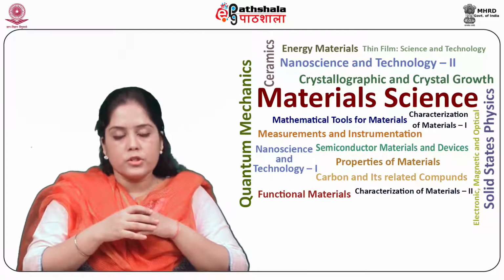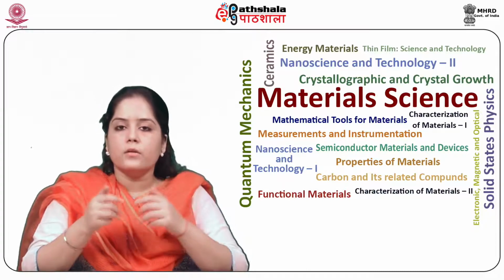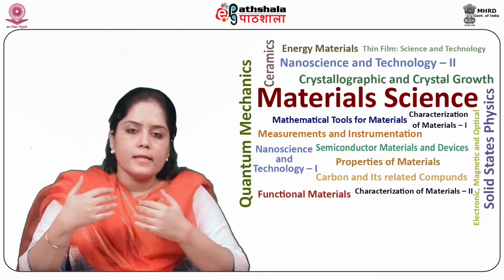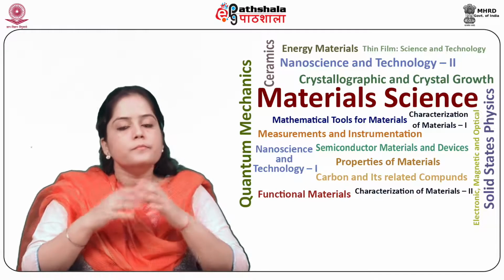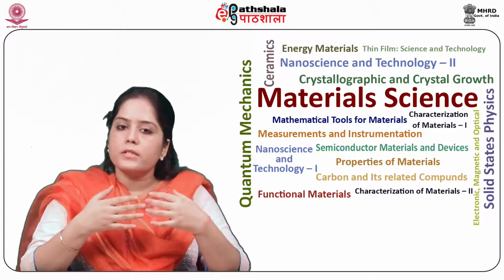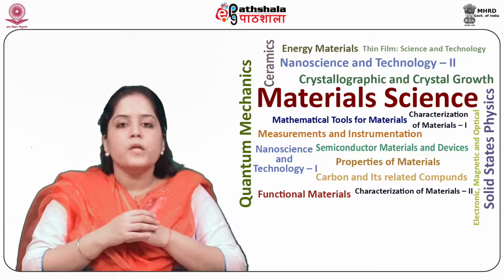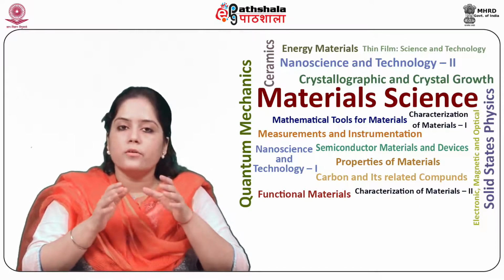microelectronic mechanical structure technique. As the name suggests, ENOS is some kind of electronic nose sensing the concentrations of various gases, similar to the functioning of our nose, which keeps on sensing the different gases and identifying the type of gas. Metal oxide based gas sensors are the most popular sensors in terms of ease of miniaturization and mass production. Metal oxide gas sensors consist of a microheater, interdigitated electrodes, and a metal oxide film.